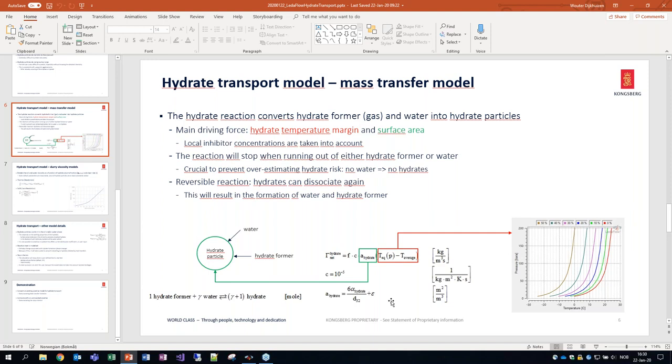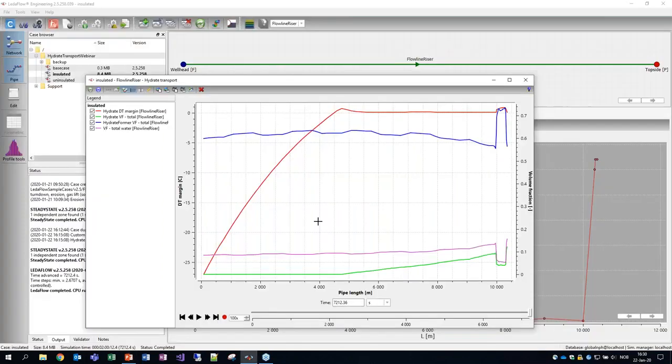Okay, we're pretty much out of time. This is a good question, actually, and something we've been looking at. Is there a minimum subcooling required for nucleation? The amount of subcooling that we need to get this reaction depends on the kinetics, but it's typically very small. In this case, you can see the subcooling is only a fraction of a degree Celsius.